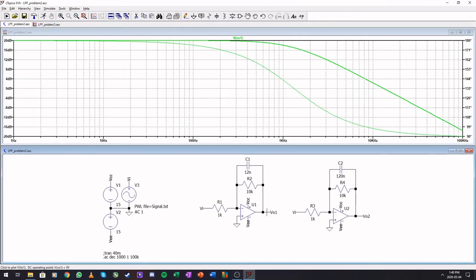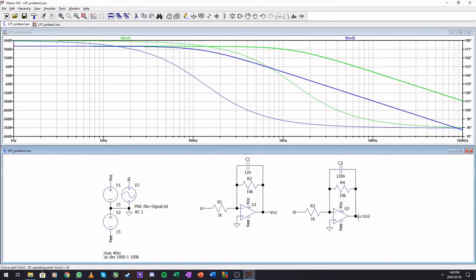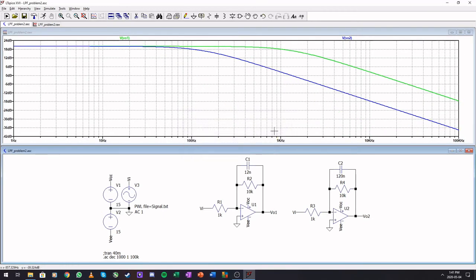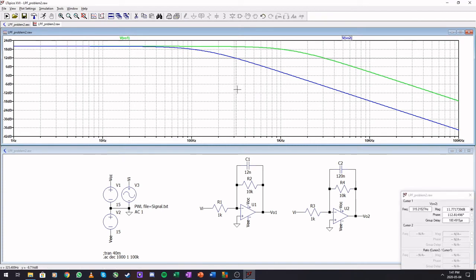This should be for 1.3 kilohertz. This should be the 133 hertz filter. Let's switch off the phase. So let's go to this signal here, and at 150, there is our minus 3 dB point. Passband is 20.